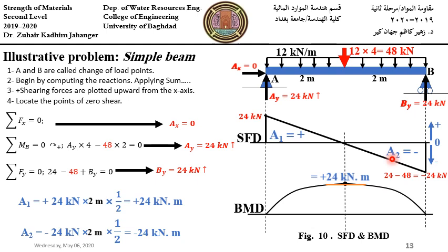Now again, this part of the shear force is non-uniform, or varying shear force, from the first degree in inclined lines. So we said the bending moment comes from integrating the shear force diagram. By integrating first degree, we get second degree lines or curve.